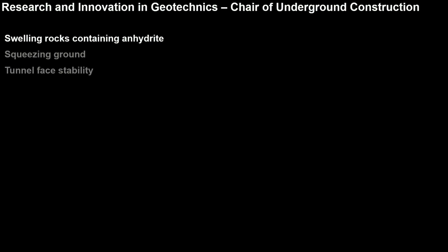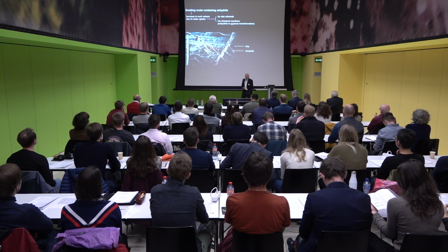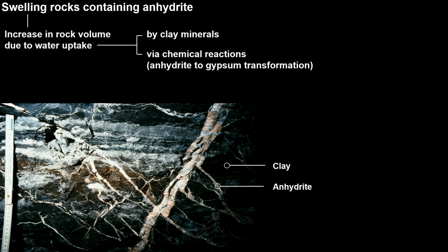So, yes. The research of the chair of underground construction focuses on 3 topics: the swelling of untreated rock, squeezing ground, and tunnel face stability. Let us start with swelling of untreated rock. Swelling is the phenomenon where certain rocks increase their volume due to water uptake. In the case of untreated rock, it is mainly due to a chemical reaction, more precisely the anhydrite to gypsum transformation.